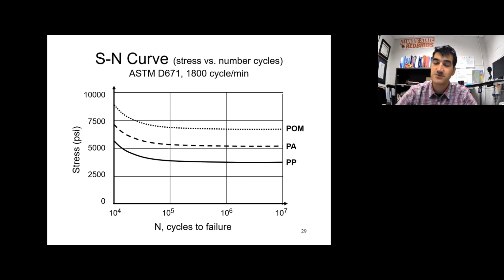So then you have your N. The point is you have your N based on the design lifetime, and then you can do that in reverse. So you can say, all right, I need it to last this many cycles. So now you know that the maximum stress you can subject that part to is this right here, and draw a line over this way. And now you know the maximum stress you can subject that part to.